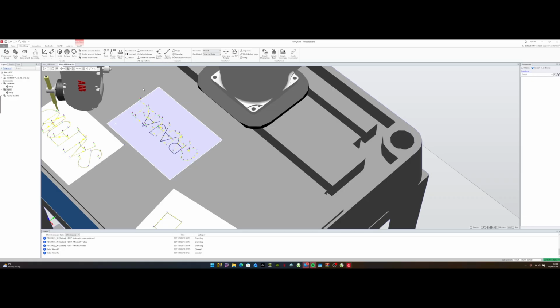And then when the robot is installed on site, then the robot programmer will jog the tool center point or the tool to where he needs it to be precisely, because in simulation there may be slight modifications on site. That's usually what happens there, but that's just like a side note you can keep.